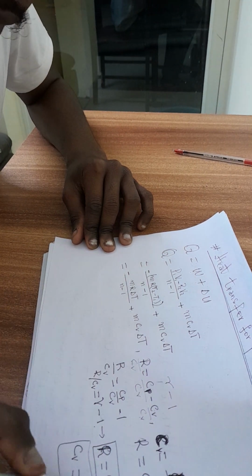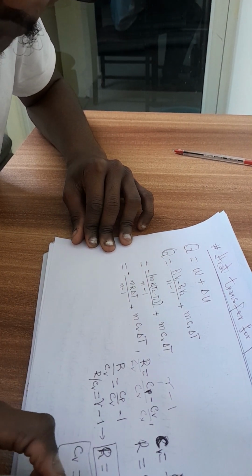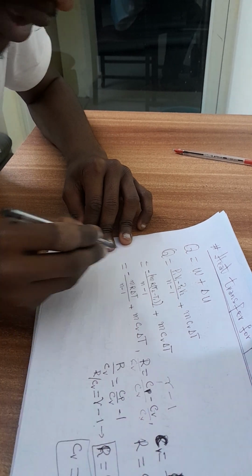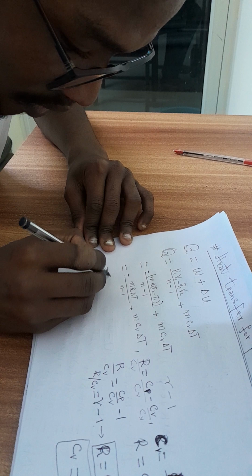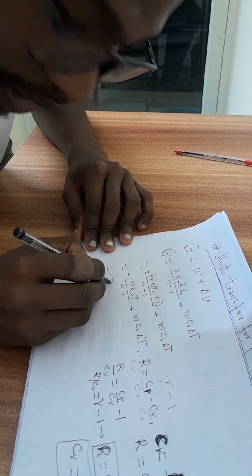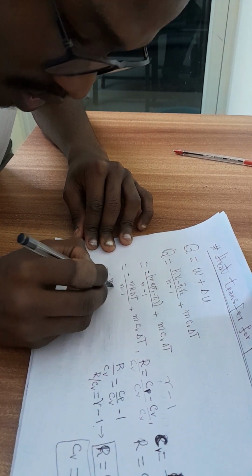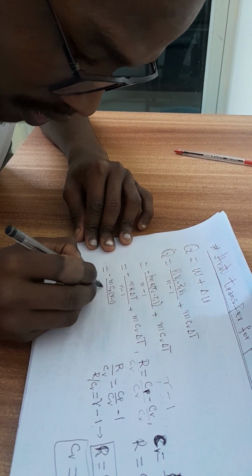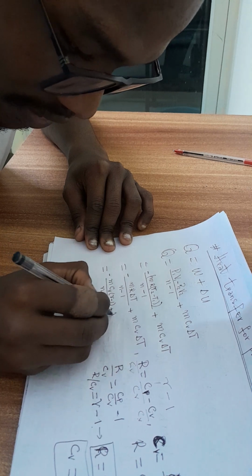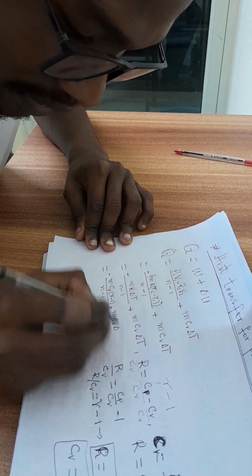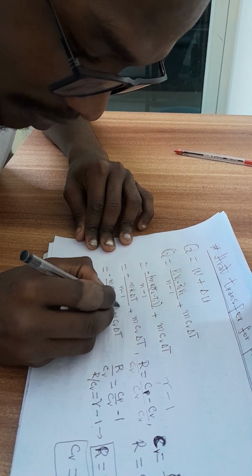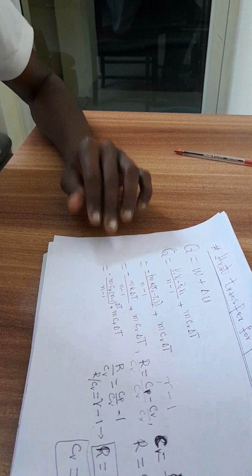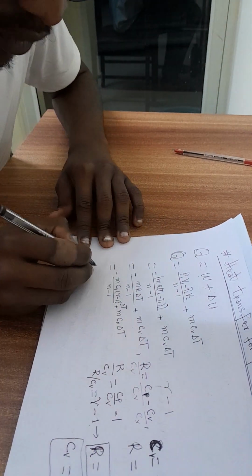So if I want to find the heat transfer with respect to internal energy, just change: where you find R, put Cv times (gamma minus 1). What do you get? You get m R, and R is Cv (gamma minus 1), upon (n minus 1), plus m Cv delta T. And here it is also times delta T, I forgot. Now from here, what do you get?